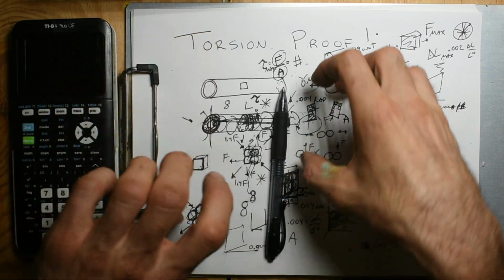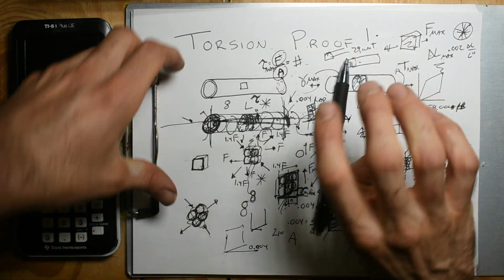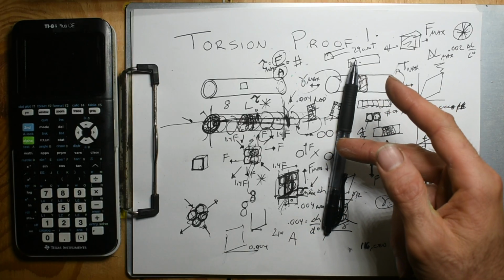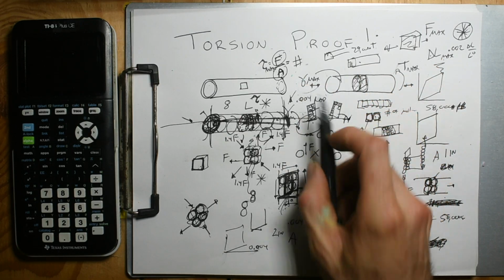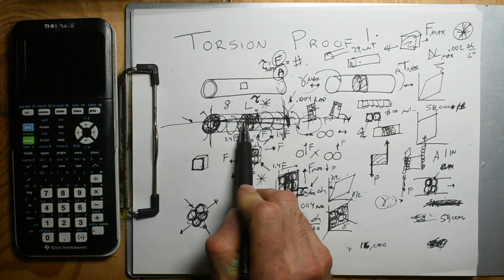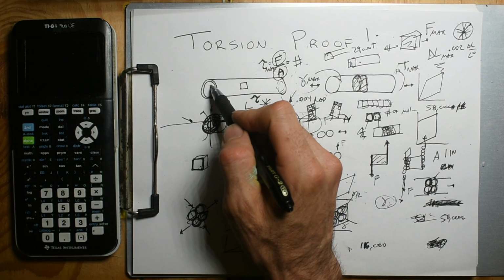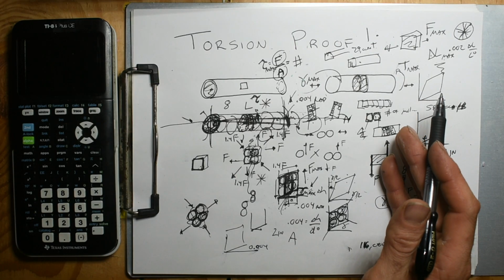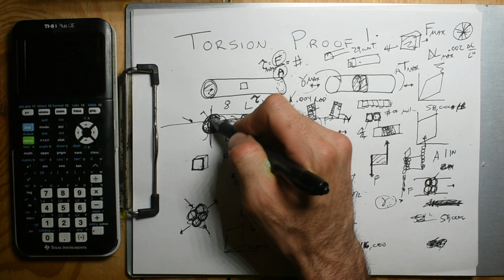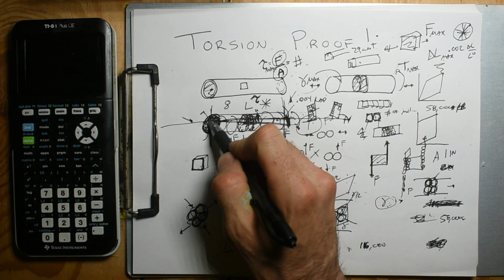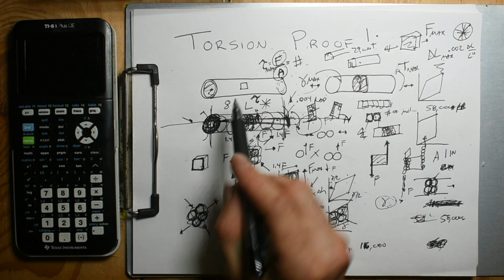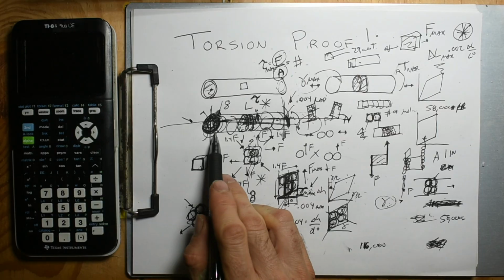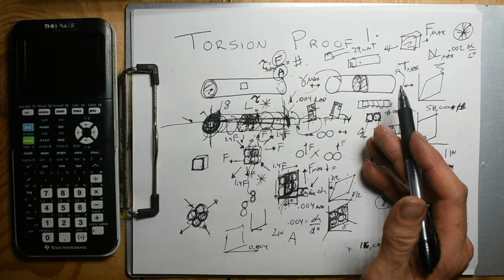and that's creating a moment, axially along here, and that has to be resisted by not only a force, but a force that's a distance away. And then these molecules are a distance away from the center. But if it's a solid shaft, the molecules near the center can't do much at all. So even if you just take the molecules like those right there, and pretend that they're at the end of the shaft, then you get a pretty decent approximation.